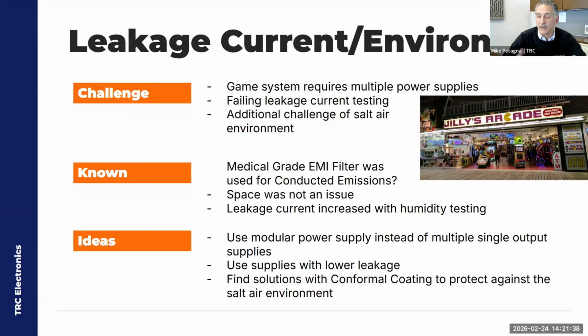You can just imagine you have different functions, and they opted to go with multiple power supplies, and that resulted in increased leakage because every single one of those power supplies has a leakage current to ground. On top of that, they had a medical EMI filter, which helped a little bit in reducing the EMI and contributed a very small amount to the overall leakage, but it still became a problem.